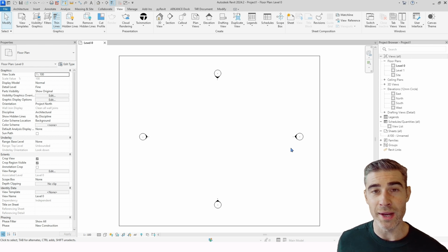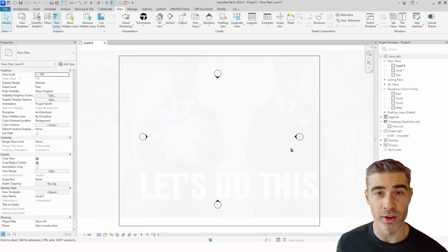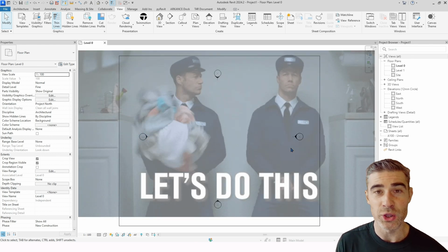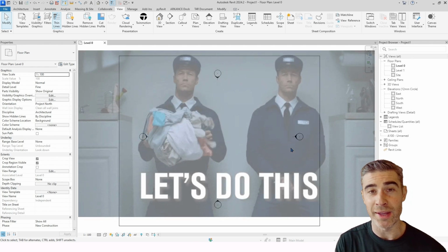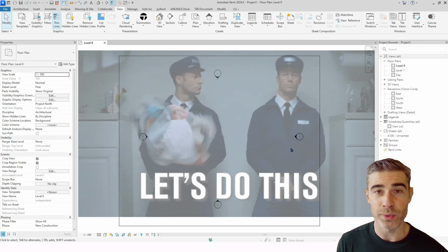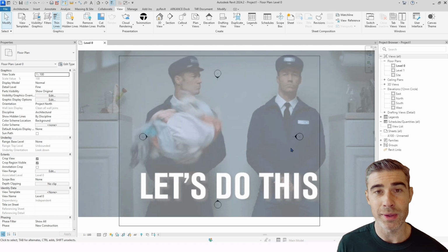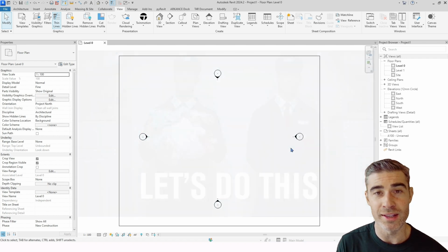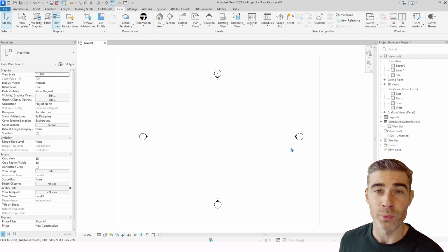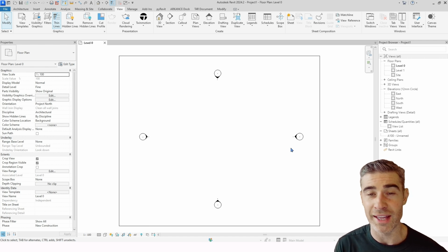The great thing about creating a separate file, we'll call it that washer file, is that you can explode it, create a mess in it, and as you're cleaning it up, start to Revitize it. So when you copy this detail, this drafting view, over to your project, it's all in Revit layers and not all of the CAD junk that you just exploded.